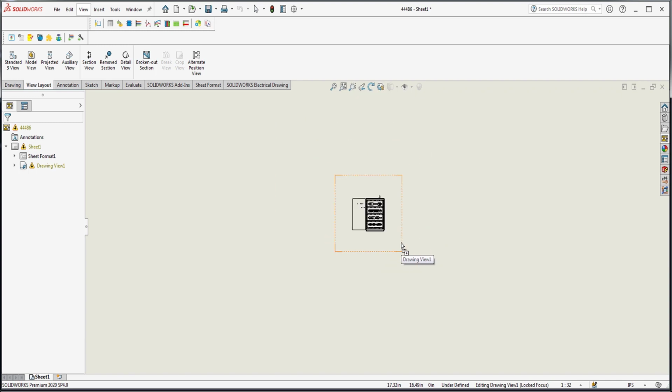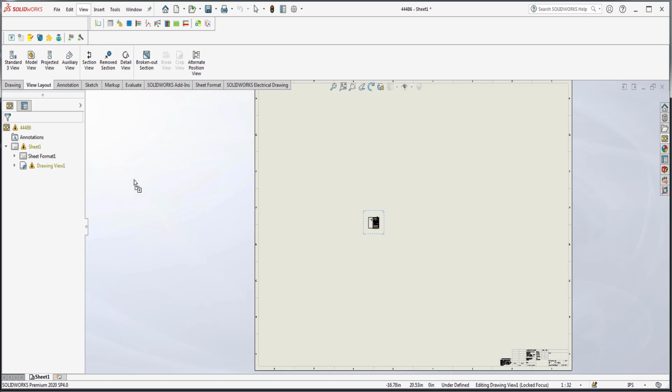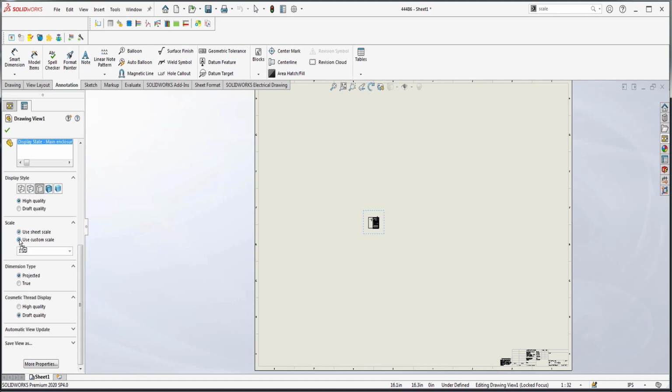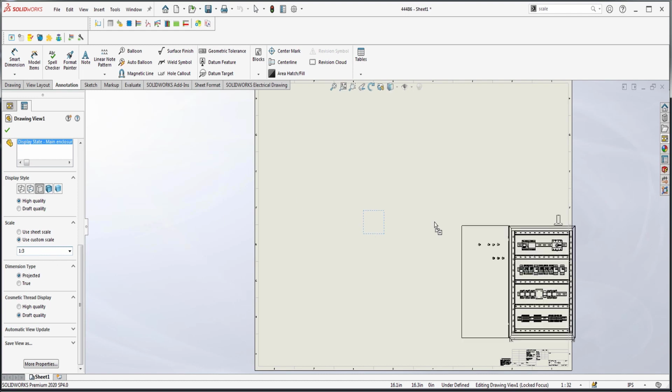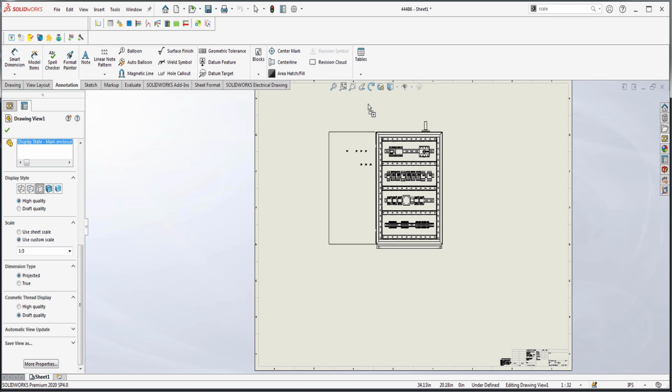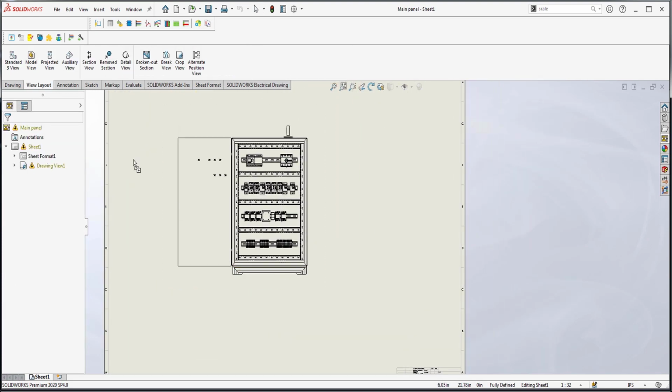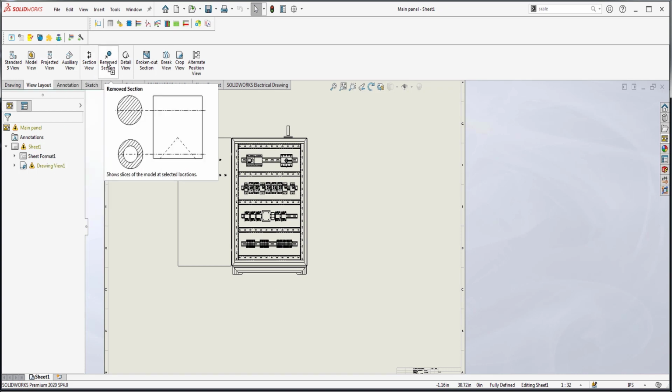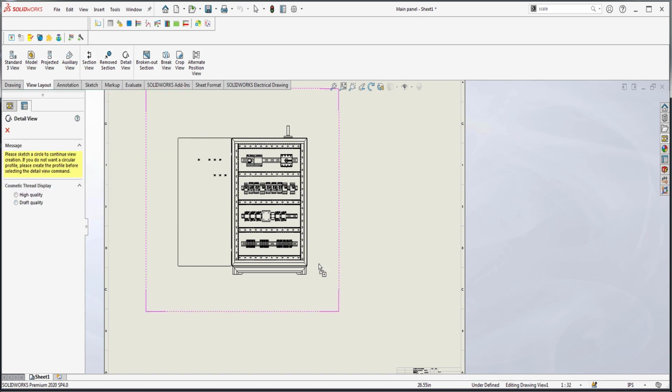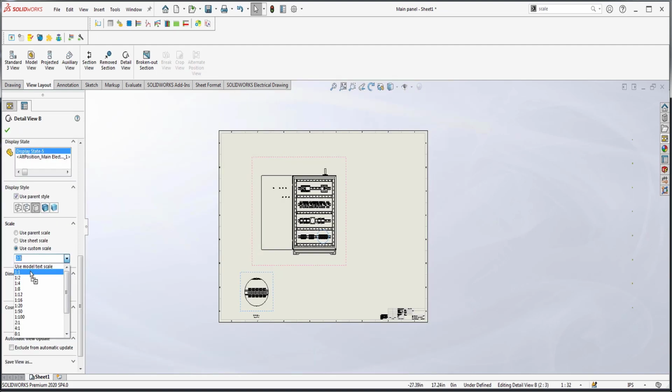We just cropped this view. It's still small. You can now scale this into your drawing set. So in order to do that, you would simply just highlight this view, and now when you do, you can then set a scale. You're not having to worry about picking each thing and is it actually picked. It's going to scale the whole thing for you because it's a drawing view. But because it's a drawing view, if your assembly changes, then so does the drawing. It's going to update.